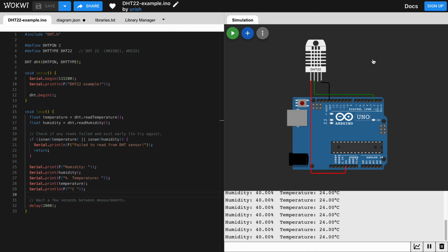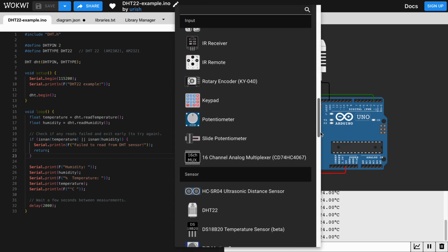If the IR remote is pointed to the AC itself, you can build a thermostat which, depending on the readings given here, we can put an if function, and we can say if temperature reading here is greater than, let's say, greater than 30, then the IR remote will switch on the AC, things like that, right?